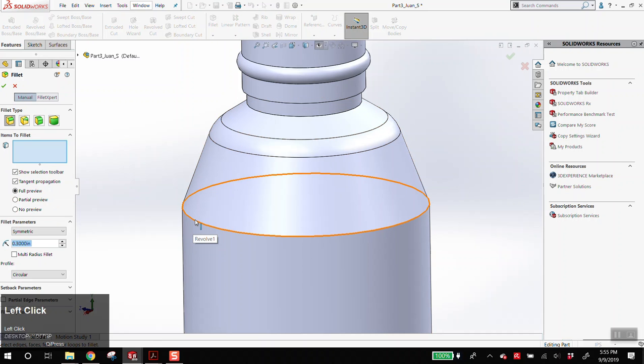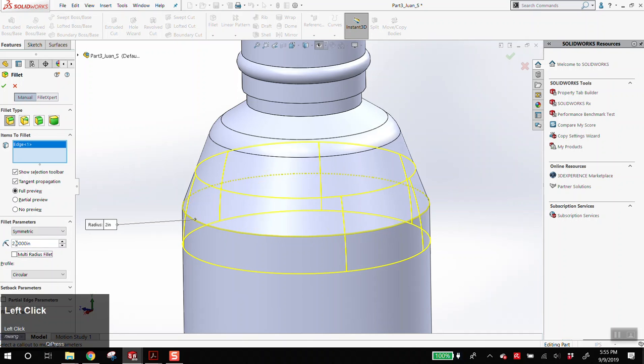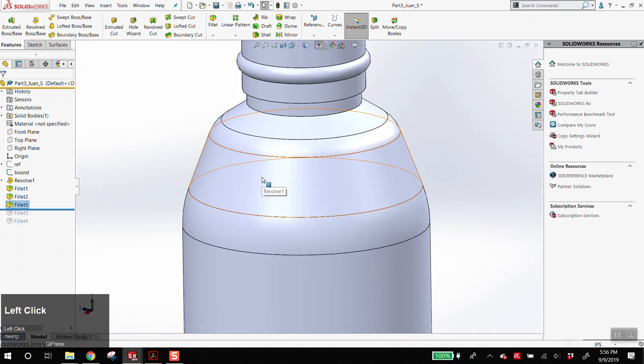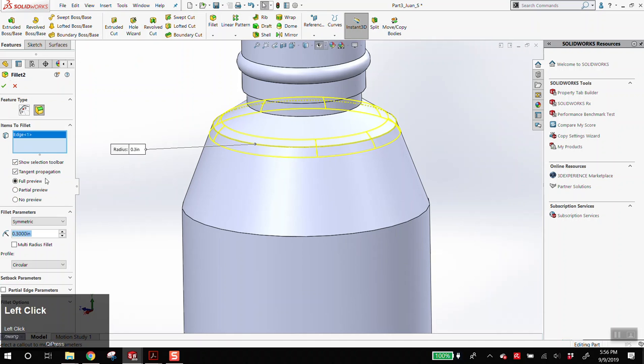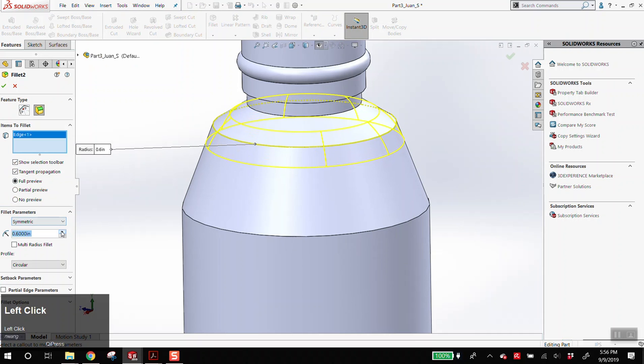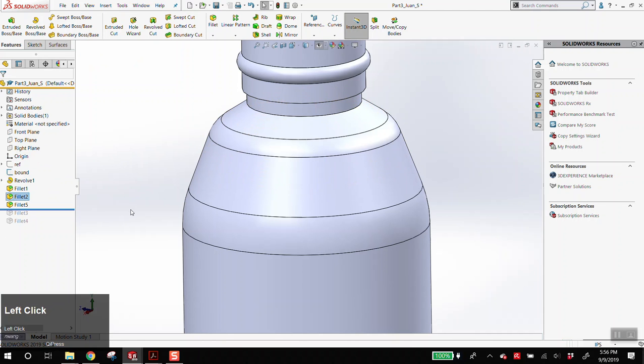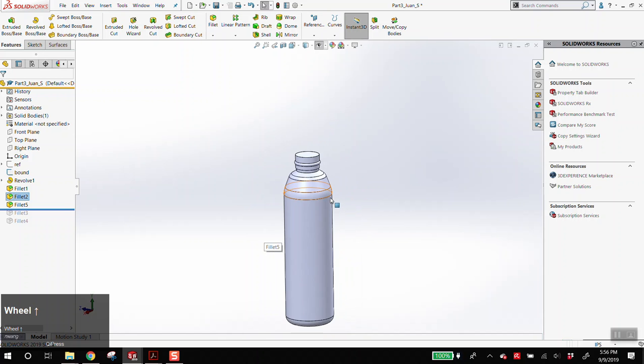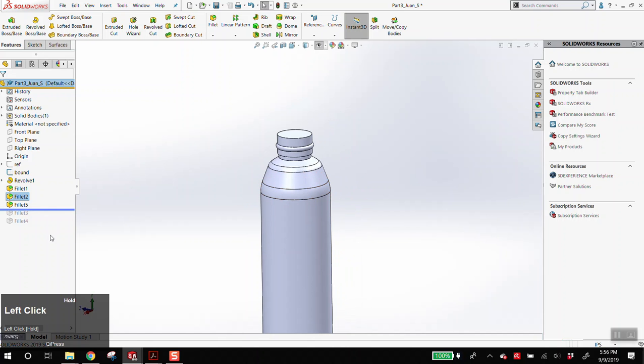I'm now selecting the fillet tool again. I'm selecting the edge. And now we're making it bigger. I'm going to assume because it was tied to the top one, that's what was limiting you. And the top one, let's look at how big we can get this. You know what, they probably ended up hitting each other is maybe what happened. That will cause a fillet to fail. But honestly, just going off gut, that looks more correct to me.